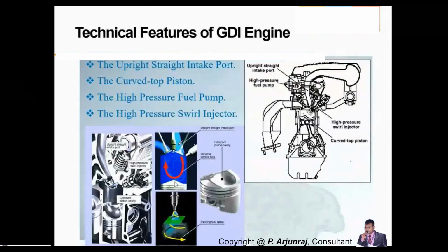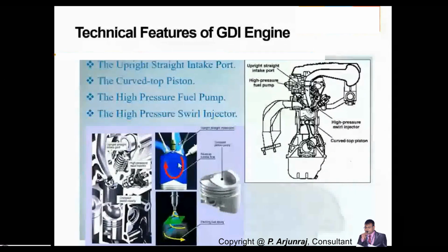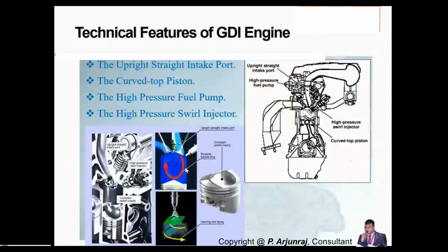Suppose this flow has more fuel than air, and when it is again mixing with the incoming system, then there is a possibility it may reduce the combustion efficiency of the incoming system where the air and fuel are already mixed. So there is a possibility of both effects, but normally we need to look into the system where you are going to get the reverse flow.